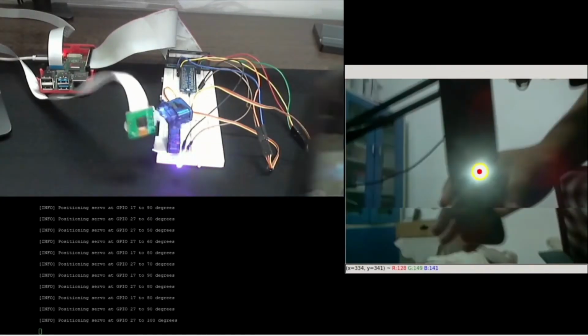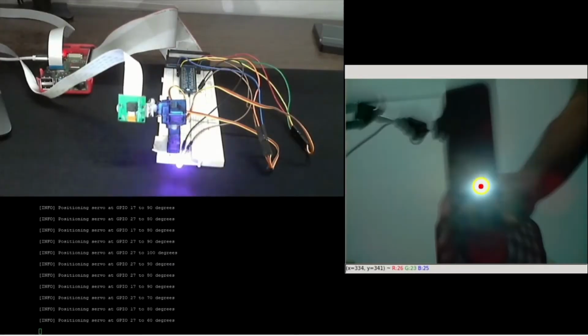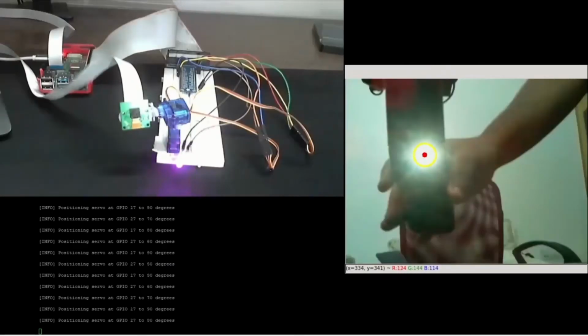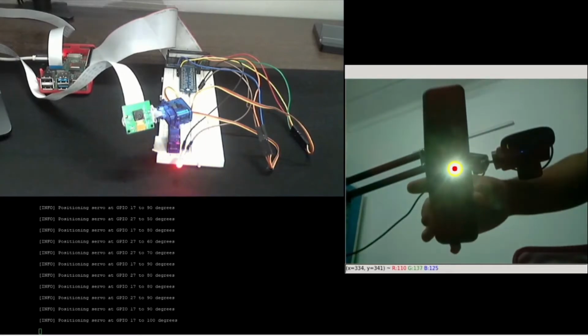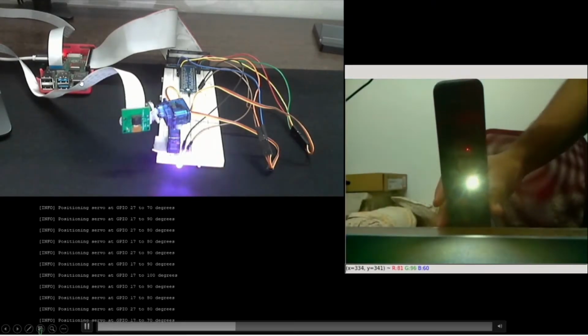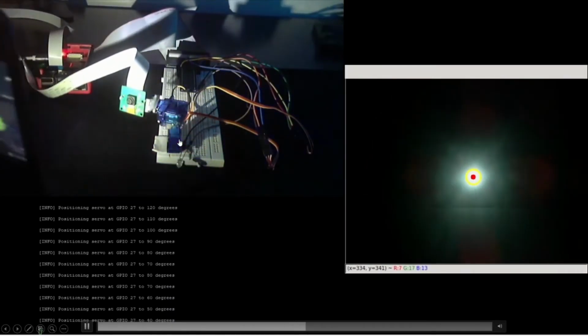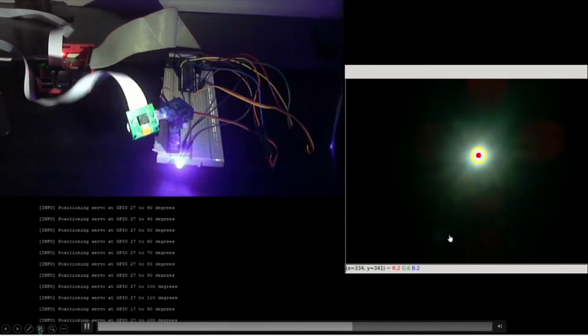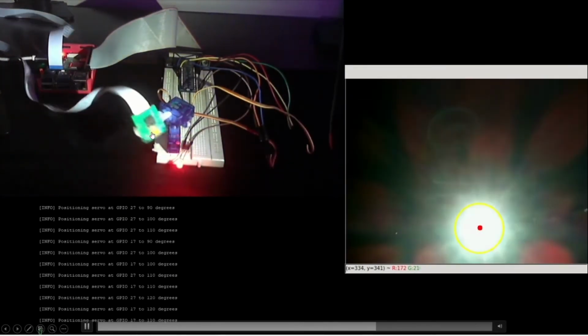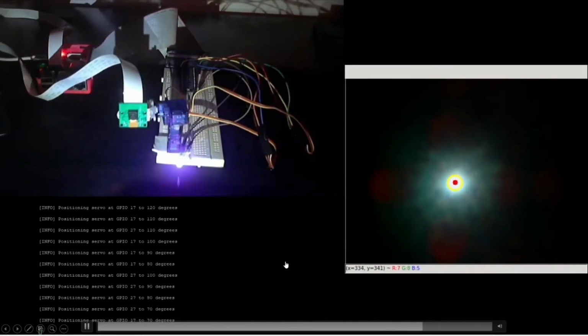So we used a microcontroller with a camera for image processing, and we're using its data to move a pan and tilt assembly with servos to get our sensor aligned with the light source again. You can see a working demo. This is a Raspberry Pi, a microcontroller, with a pair of servos, which is working as a pan and tilt assembly. This is the positioning data, and on the right side you can see what the sensor receives, and it's doing all the processing. So it's tracking. As you go right, it goes right, go left, it goes left.